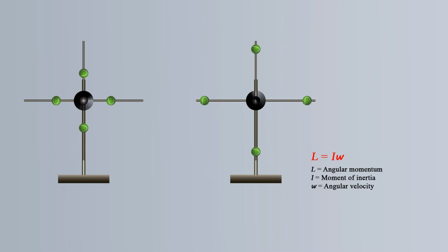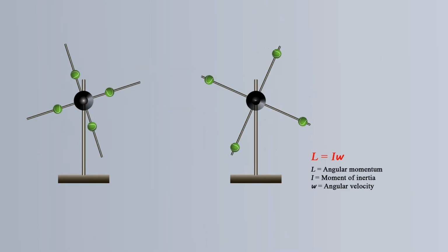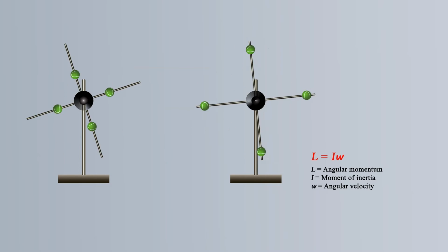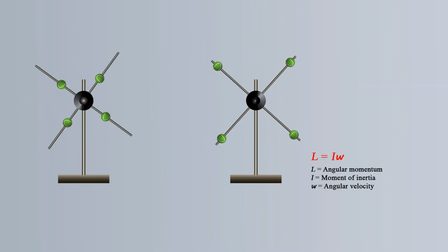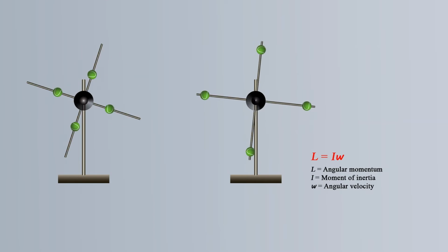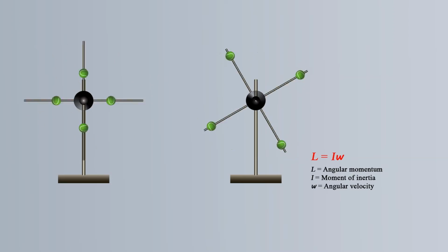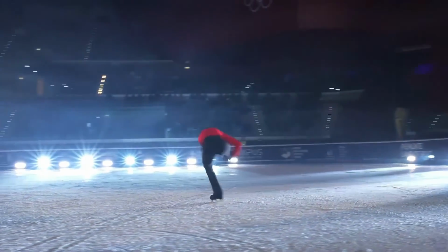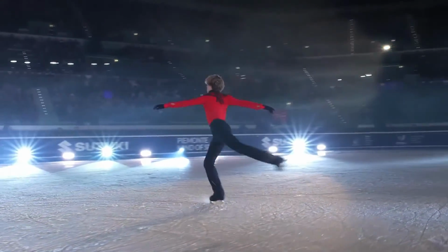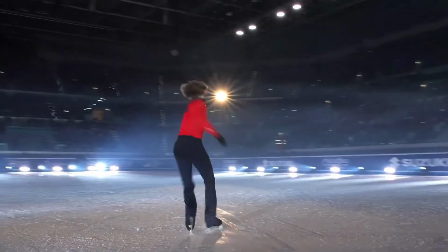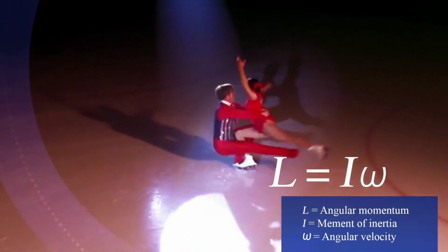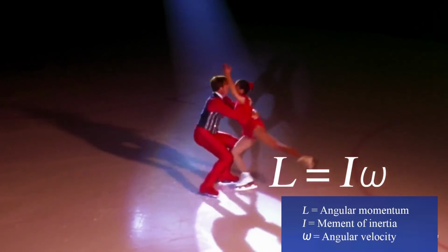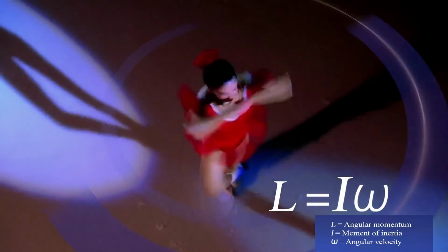Changes in angular velocity, known as angular acceleration and deceleration, take place as the mass of a rotating body is moved closer to or further away from the axis of rotation. The speed of the rotating mass increases or decreases in proportion to the square of the radius. An excellent example of this principle is a spinning ice skater. When skaters extend their arms, their rotation slows down because the center of mass moves farther from the axis of rotation. When their arms are retracted, the rotation speeds up because the center of mass moves closer to the axis of rotation. The reason for this is that the distance between the center of mass and the axis of rotation, times the rotational velocity of the mass, will try to remain constant.